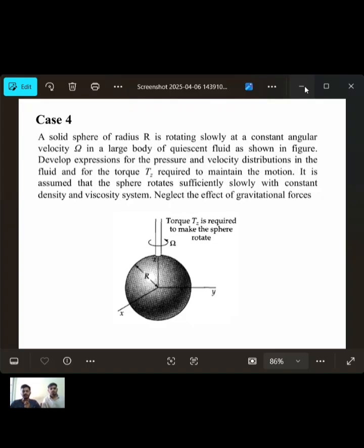And if the fluid is honey or any oil or any fluid with a higher density than water, then much more torque will be needed. Also, this torque technique is used in viscometers to measure viscosity. This is our practical usage of this problem. Now, centrifugal pressure means the negative pressure at the equator.